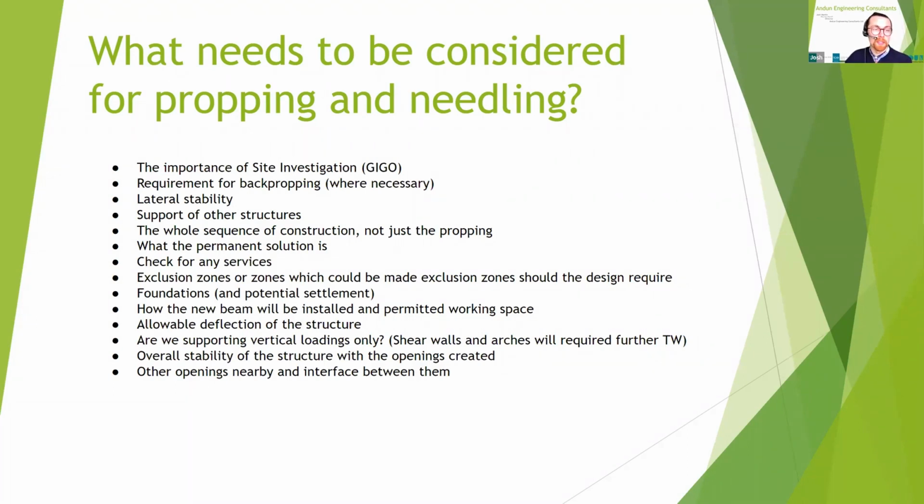The loadings that must be considered: are the loadings all coming from above, so it's just vertical support, or are there any point loadings, and are they evenly distributed? Overall stability of the structure: who is taking responsibility for the overall stability? It may be that a particular design is packaged off just to look at that localized design. But if there are multiple openings being made in the structure, whose responsibility is that, and the interface between them as well?